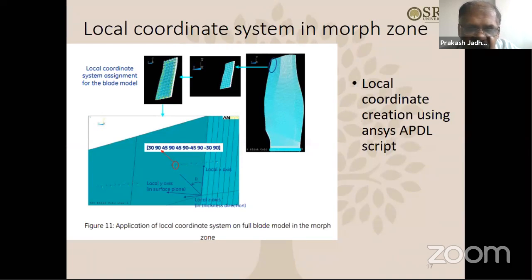So doing all this calculation on the panel was okay, and the panel is showing some encouragement, which is fine, but the blade is totally different, very complicated. So how do you do that in the blade? We took the actual blade ANSYS model, and as was discussed earlier, we chose that trailing edge region there. The trailing edge region we kind of separated, separated meaning basically inside the blade only, but treating that area separately, and we assigned a local coordinate system there.